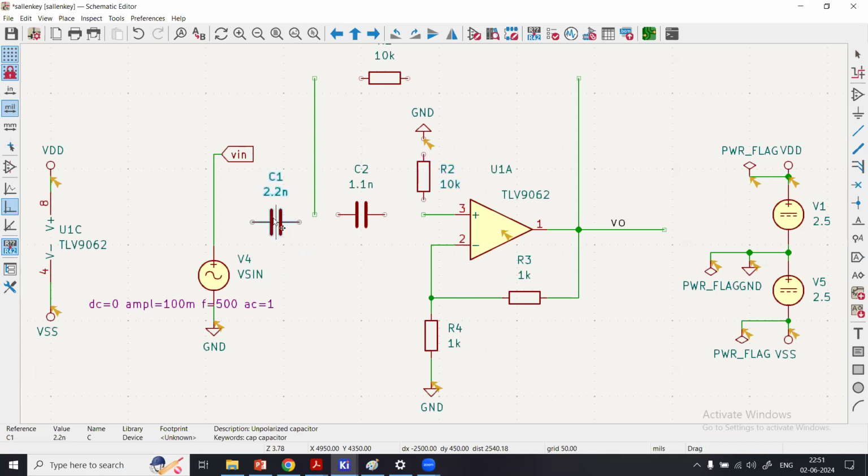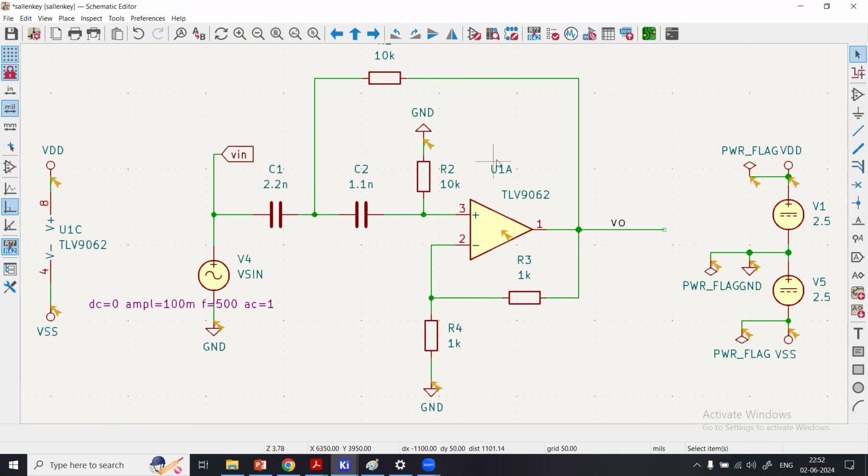So this capacitor goes here, and then I will connect all these components through the wires. You can see that I am slowly swapping the position of the resistors and the capacitors in my circuit, transforming the originally second order active low pass filter using Sallen-key topology into some other form of filter, not in a moment, but in time to come. As we progress, we are going to see what kind of behavior this circuit will exhibit, what kind of filter response specifically.